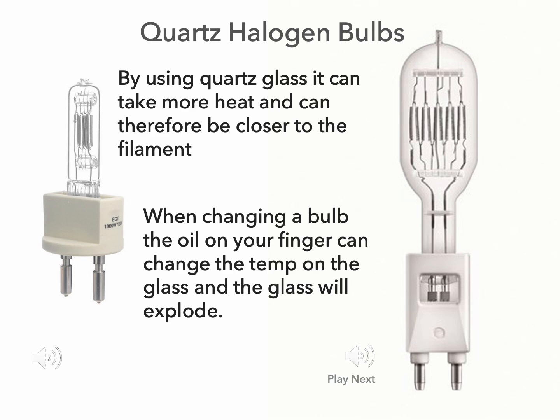When you change a quartz halogen bulb in a fixture, well, there are certain safety precautions. One, make sure the light's unplugged. The other thing you want to make sure is that you don't put your fingers on the quartz glass itself, because when that light turns on, the oil in your fingers will change the temperature on the quartz glass, therefore causing it to crack.